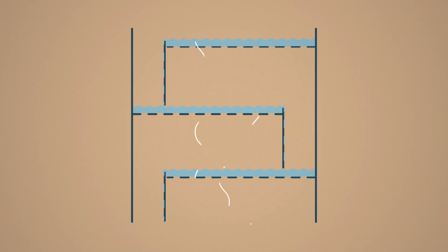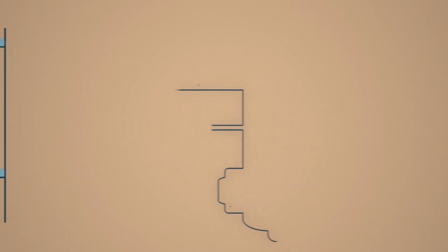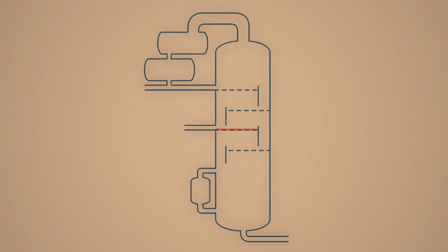Fractionation applies this different vapor pressure to each liquid comprising the mixture. The process includes repeated interaction of vapors with reflux, liquid obtained by partial vapors condensing. This process occurs in the fractionating tower. Initial mixture is fed to the feed tray. It is usually liquid, but sometimes it can be vapor or vapor plus liquid.